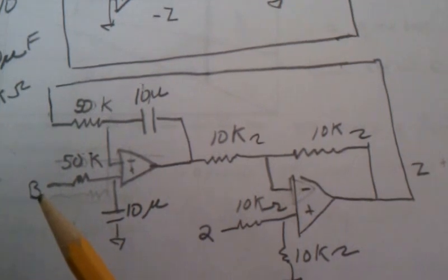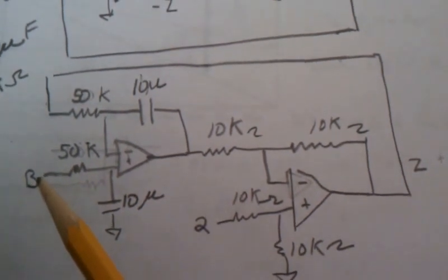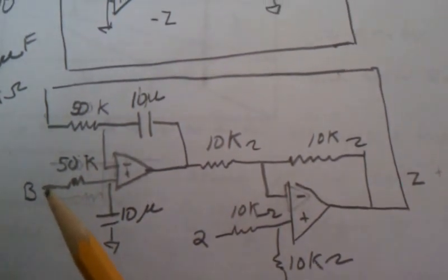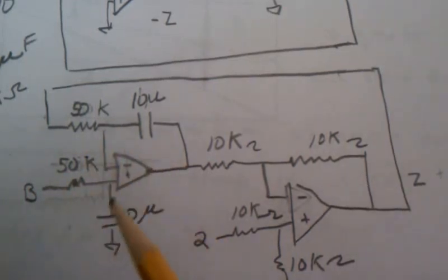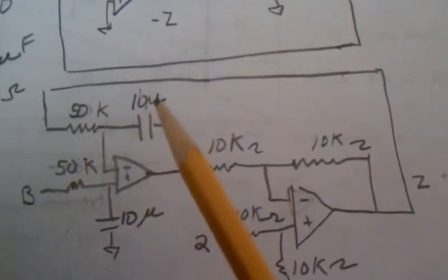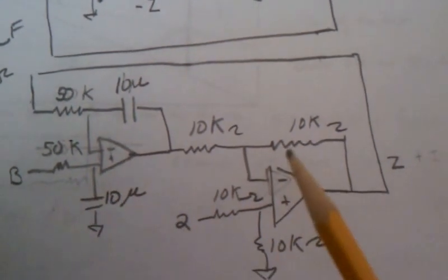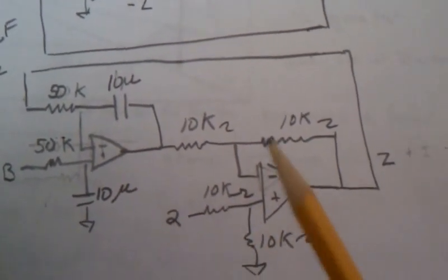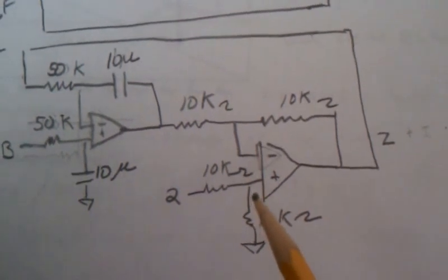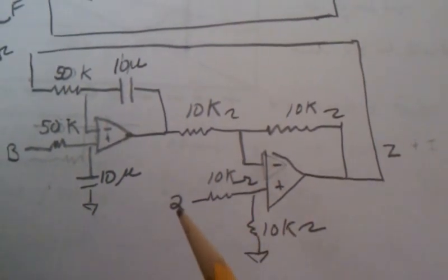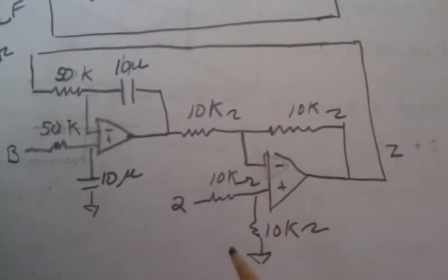Inverting usually involves another op-amp somewhere for an inverting amplifier. So if I use this configuration and keep tight tolerances on my capacitances, I can bring in B here. And then on the initial condition, if I use this configuration that we've talked about prior, I can get my 2 volts of initial condition there.